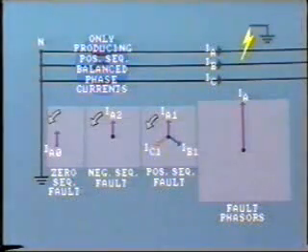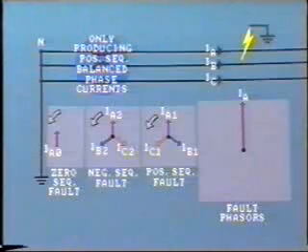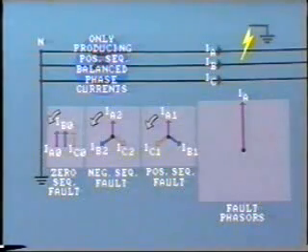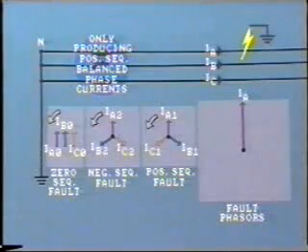Now that we have located IA2, we can draw in the other 2 negative sequence components, IB2 and IC2. We can also now add in the zero sequence current components, remembering the characteristic that they are always in the same angular direction.